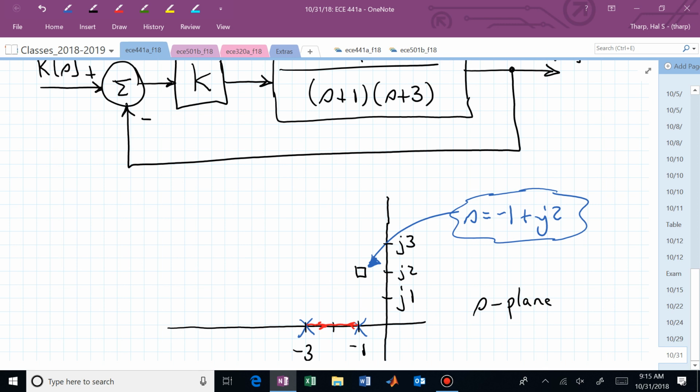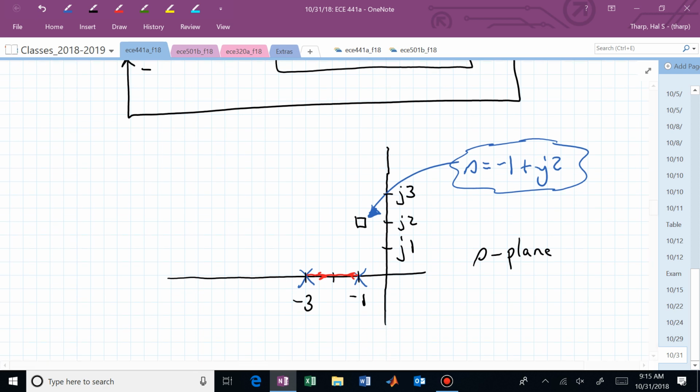Our sigma sub A is right between those two poles, and that's true always. When you have two poles, and that's it, the root locus will be going towards each other with negative feedback, and then they split right between each other, halfway between, and then one goes up and one goes down.